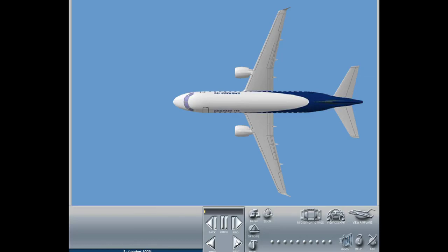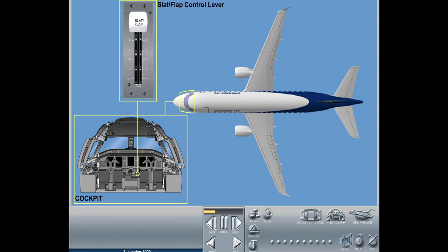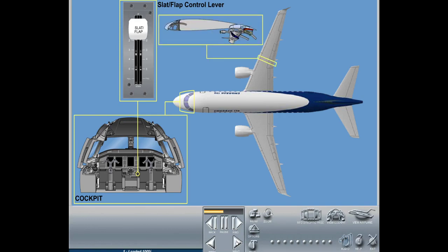The Embraer high-lift system consists of two actuation systems, one controlling 8 slat surfaces on the leading edge of the wing, 4 per wing, and the other one controlling 4 double-slotted flap surfaces on the trailing edge, 2 per wing. A single control lever, located on the center pedestal in the cockpit, is used to control the movement of slats and flaps. There are 7 slat-flap control lever positions, defining the combined positions of the slat and flap surfaces. Slat and flap motion is sequenced such that slats extend first, and flaps retract first when the motion command requires both surfaces to move.